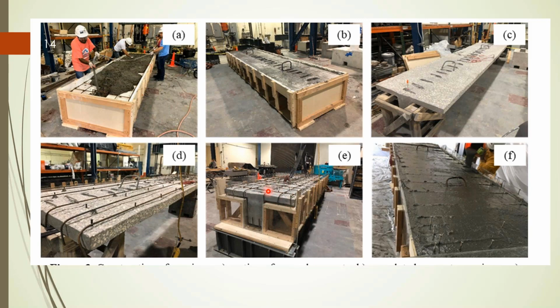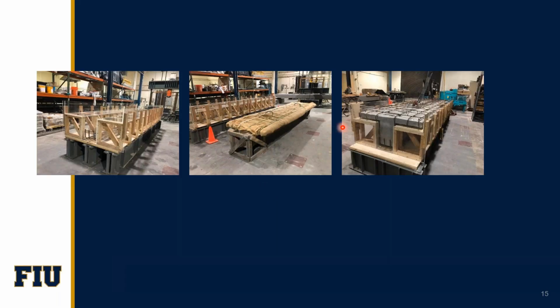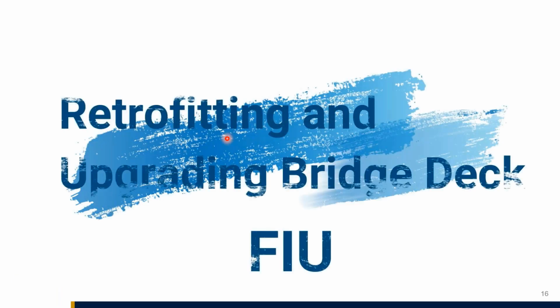Once we cast the T-beam, which represented the damaged T-beam, we placed it in the epoxy formworks. Before putting it there, we wrapped it for 24 hours with wet burlap, because you have to have exposed aggregate and a wet surface, and then we placed it in the glass formworks.